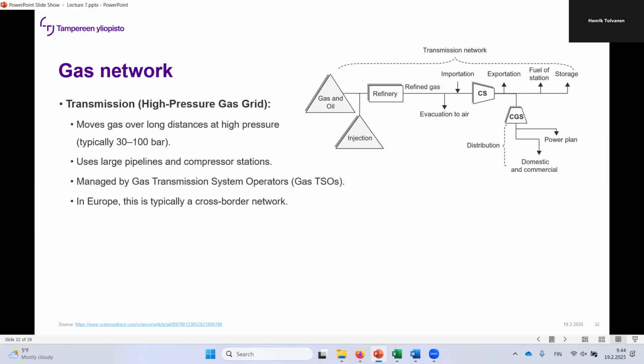build. And the driving force in here, again, is the pressure. That's the same thing as in the district heating network. If you have a flow, the driving force is going to be a pressure. If you have electricity flow, it's going to be the voltage difference. So you have to have a higher pressure at the refinery end. That's why you have these compression stations. In the refinery, you would have a compressor that would pump up the gas pressure, and then it would start flowing through the pipeline. And the pipeline resisting factor is going to be the friction. So the smoother the pipe, the less the friction.